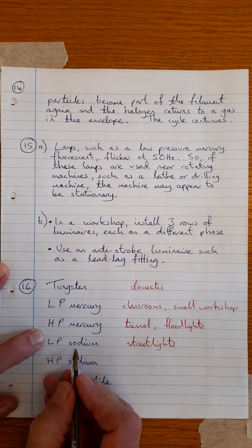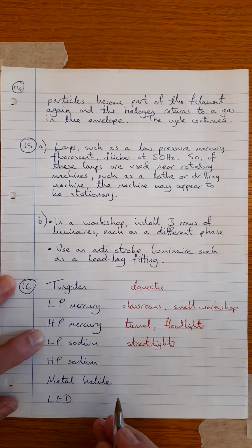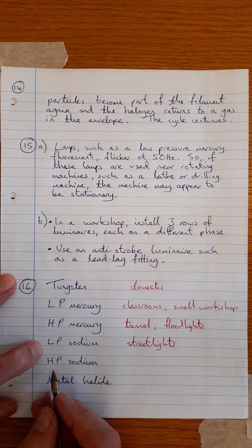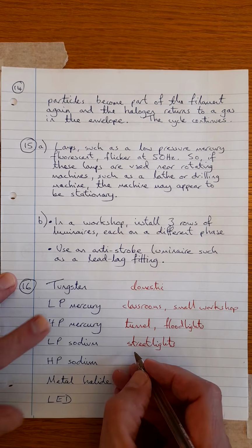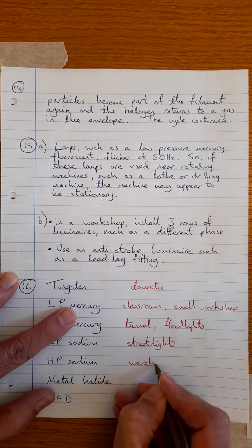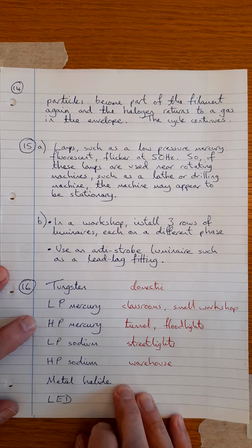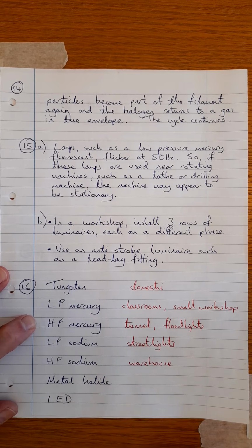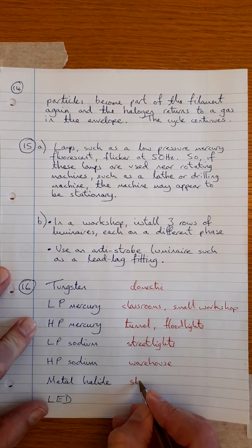Just to stress, I've said it's orange. Technically, the colour of the light is yellow. And speaking of which, that takes us to high pressure sodium, which is a more yellow light than that. It's more pleasant and more comfortable. And they may be used in all sorts of places, like a warehouse. Perhaps an outside five-a-side football pitch. Colour rendering isn't fantastic, but I have seen them used there. So metal halide, quite commonly nowadays stadium floodlights.